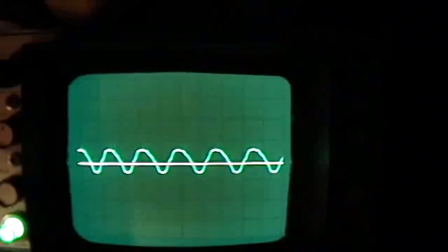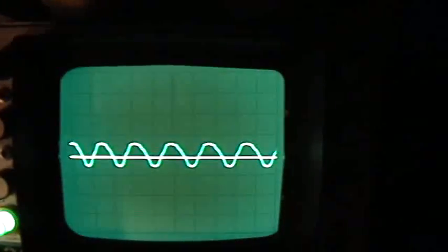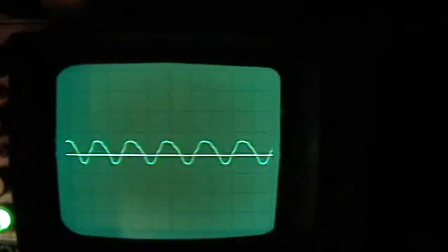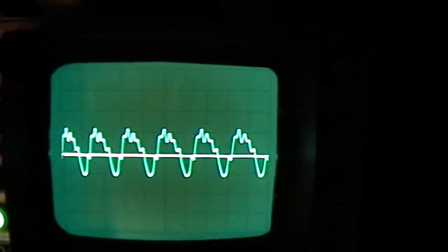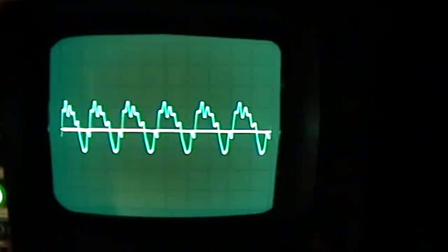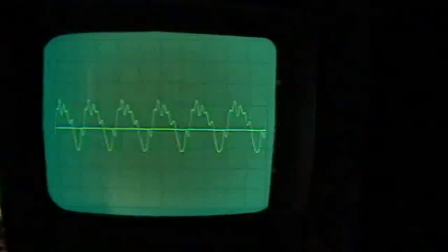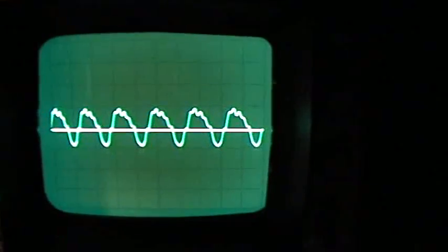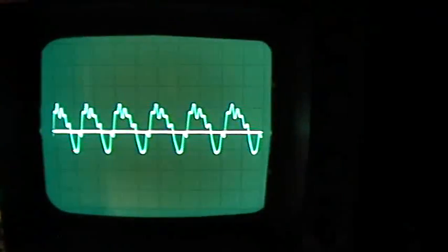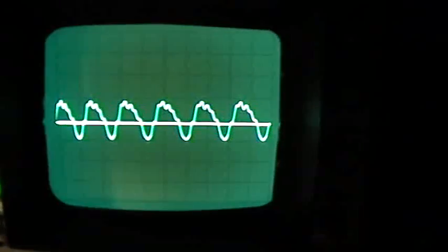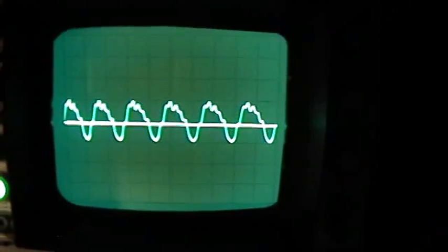Also, by varying the power input to the 555 timer, I can turn those oscillations into almost a pure sine wave, which I think is really neat. If you get a lot of power into the 555 timer, you get more and more distortion until finally the oscillations actually stop and the MOSFETs begin switching. Why they begin switching, I don't know, but they do a little bit.